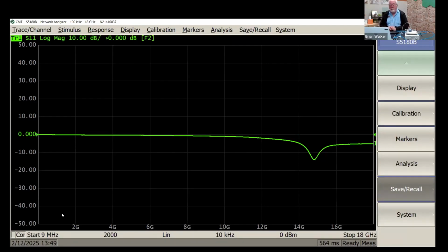Well, because in the time domain mode, we do a special trick. We take these harmonically related points and we flip them around 0, and we generate negative frequencies, -9, -18, -27 to -18 gigahertz. And we populate those negative frequencies with the complex conjugates of the reflections that we measure in the positive domain. And then we take the inverse Fourier transform of that.